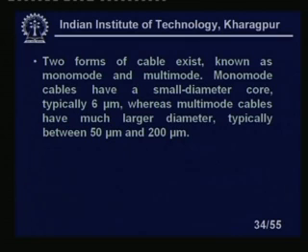Two forms of cable exist, known as monomode and multimode. Okay. You have monomode fiber, we have multimode fiber. Launching the light in the monomode fiber is very difficult, because you have to use a very directional light in the case of laser, whereas in the case of multimode fiber I can use ordinary light, LED. That saves a lot of cost.